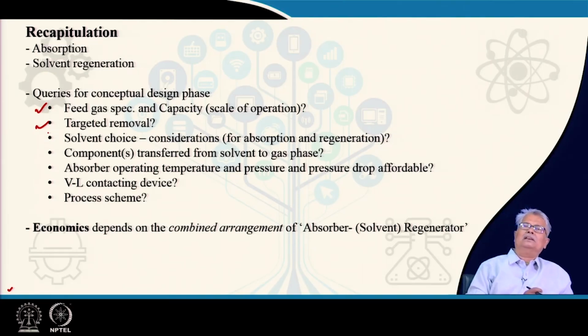We definitely, in our simplified treatment, will be considering that it is only the solute component which is transferred from the gas to the liquid phase. However, in reality, some small amount of some component or all components of the solvent may also get transferred from the liquid to the gas phase itself. A common thing being, when the gas is unsaturated with respect to the solvent liquid, some amount of vapor phase transfer or vaporization of the solvent and joining the gas phase will definitely be happening.